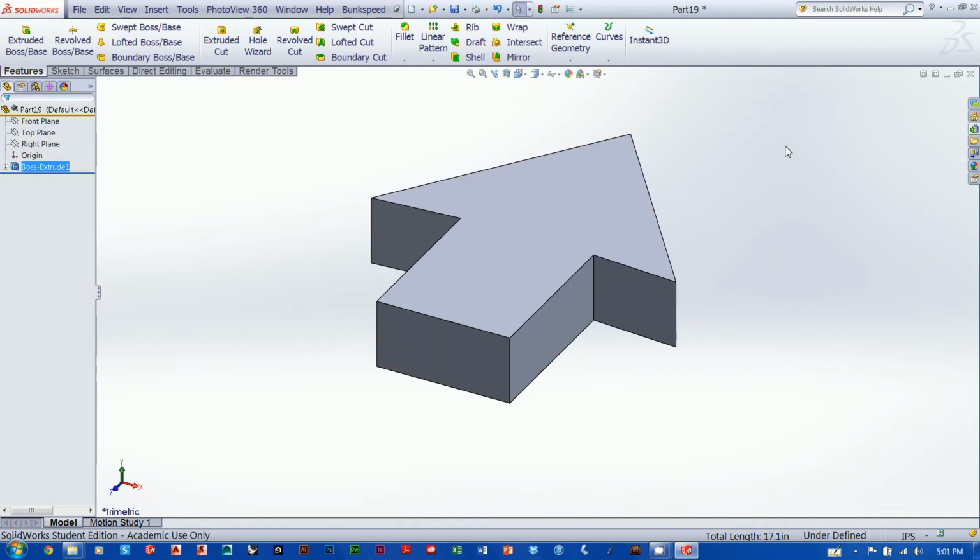And there we go. Now, we notice a couple of things. First, we notice that this thing is shaded. In other programs, like Rhino or Alias, your model isn't shaded unless you ask it to. So this is okay. It's just unique to SolidWorks. SolidWorks always shades its 3D objects. If you go up here to the heads up display, you can change that in the display style.